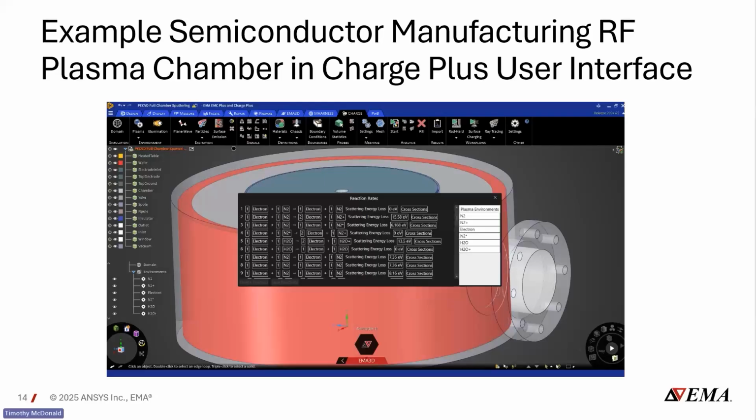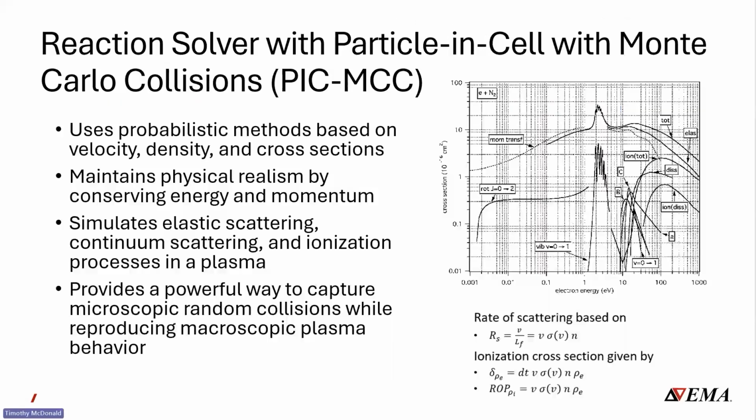I mentioned the chemical reactions that happen. Essentially, one of the key innovations that we have is a reaction solver with particle-in-cell and Monte Carlo collisions. So that's PIC-MCC. So what is going on here? The reaction solver with PIC-MCC provides a self-consistent way to simulate particle transport and interactions in the plasma. The reaction solver determines particle scattering and collision events probabilistically based on the underlying plasma parameters and cross sections.